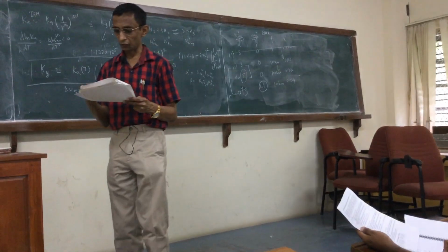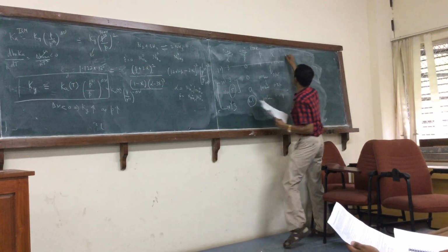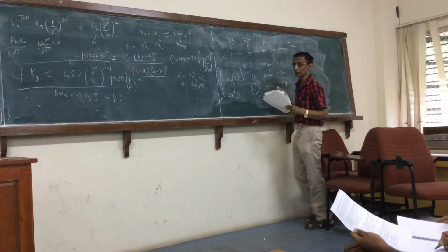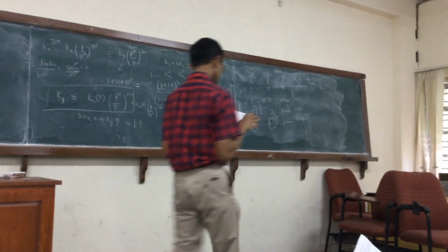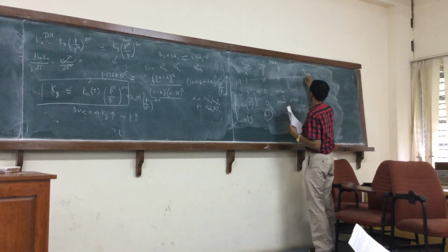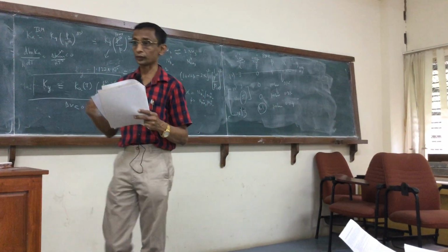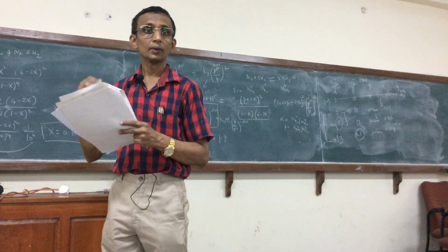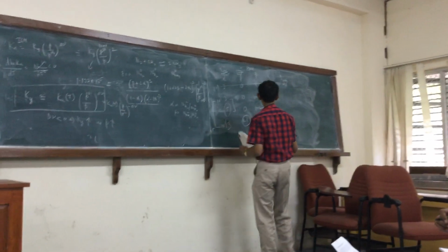But another measure of the efficiency of the whole process, the conditions on the equilibrium, can be given by calculating the number of moles of ammonia, because that's also a final objective, how much ammonia is actually formed. And here you will see that the first one is very low. So you go back to the formula that we had for YNH3. You can also calculate the final composition of the reaction mixture. So what we've got is X. From that you can calculate the mole fraction of each of the components.